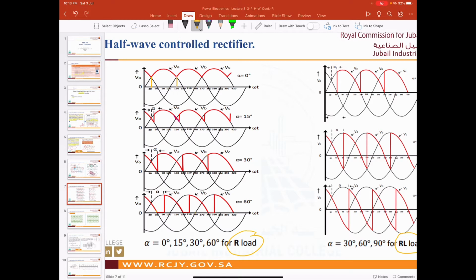Now in the three-phase half-wave controlled rectifier, if we have alpha is 0, it will act like the uncontrolled one. Okay, now this is like the uncontrolled one. It is easy, nothing is different. But here we have something very important to mention. Now in the uncontrolled rectifier, we said alpha is 30 degree. Now here is different. We said like this because it was the uncontrolled one.